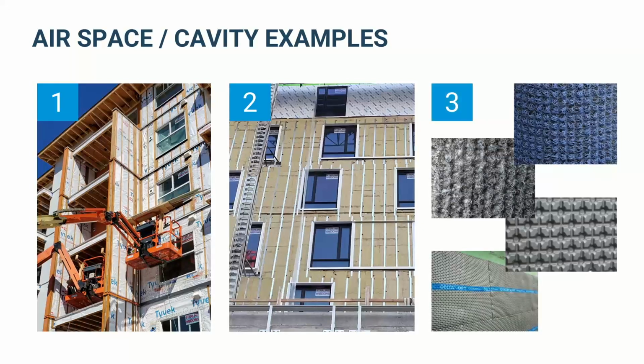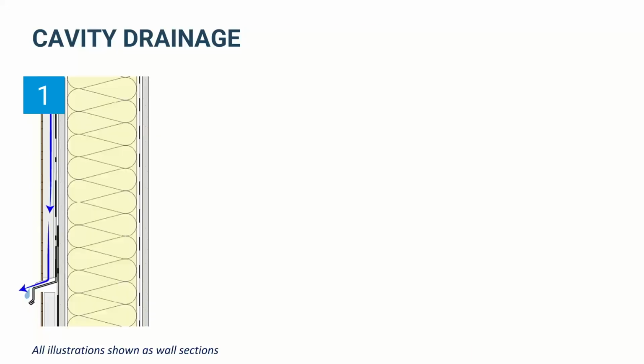And then we also see some engineered drain mats or composite materials, so either like an entangled mesh or a dimple board. A lot of those are commonly used in residential. You can put those up behind stucco or thin stone veneer. Some of them actually have lath built into it. Sometimes you put a lath over it. But that's another great way to maintain that drainage cavity. Right.